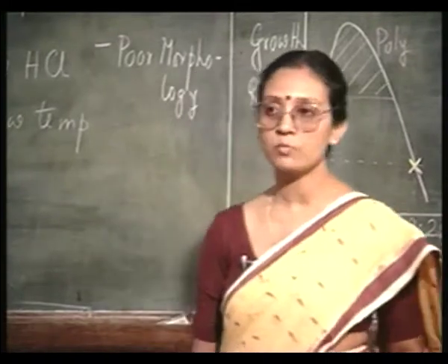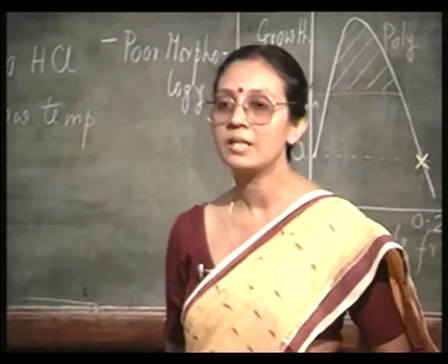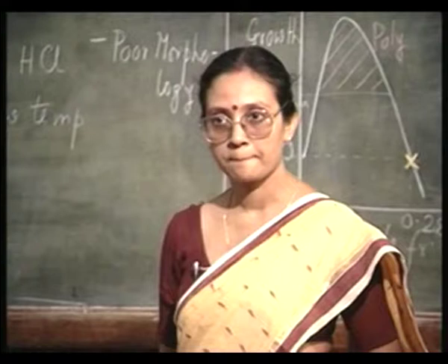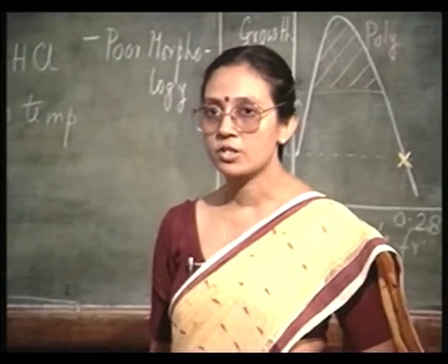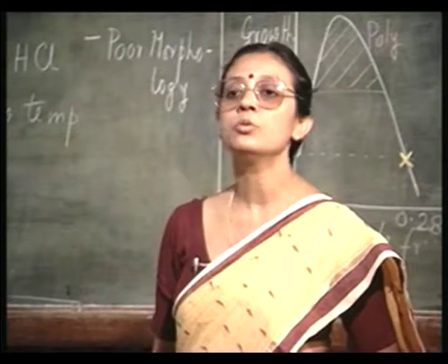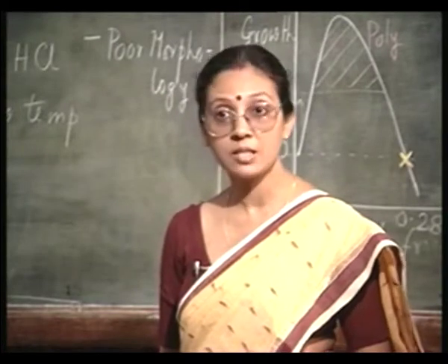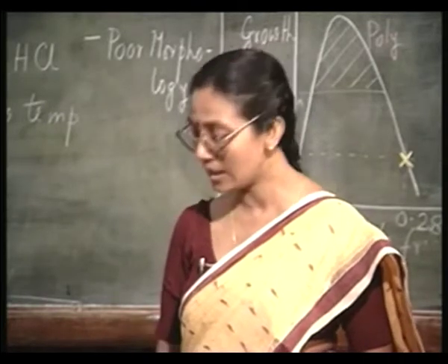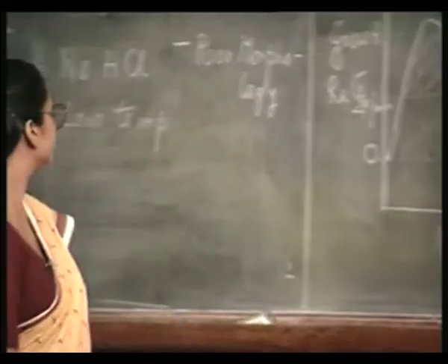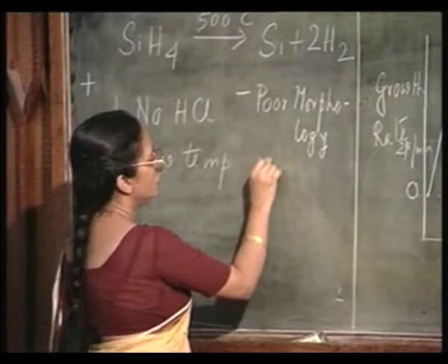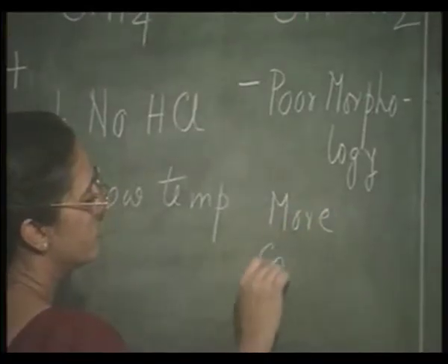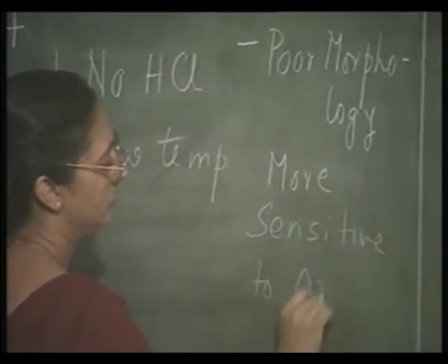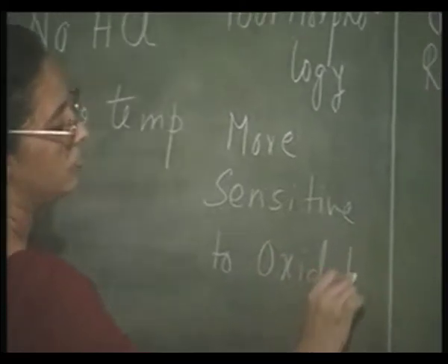By that I do not mean that you can have the system full of oxygen, but if there are trace amounts of oxygen, the reaction is more tolerant to that. In contrast, the silane reaction is extremely sensitive to the presence of oxygen. That is a major practical concern, because in practice it is very, very difficult to really get rid of oxygen. So, it is also more sensitive to oxygen.